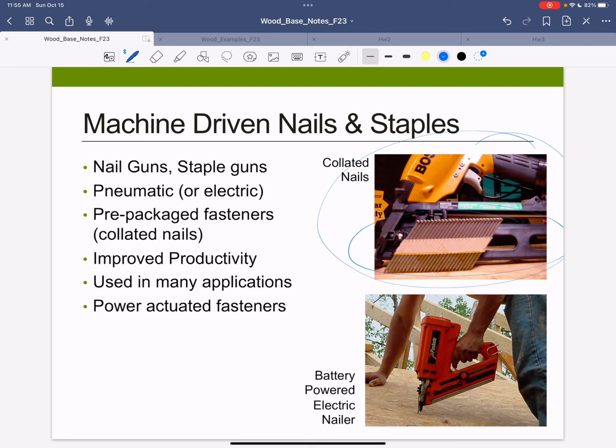But actually these are used on construction sites. There are different sizes, and you have to have a gun that can handle the size range that you're trying to shoot, which is why you'll end up with a smaller brad nailer or finish nailer or framing nailer. There are also staples that are effective, for instance, if you're putting a coating over an exposure, though that's really nicely done with staple guns.